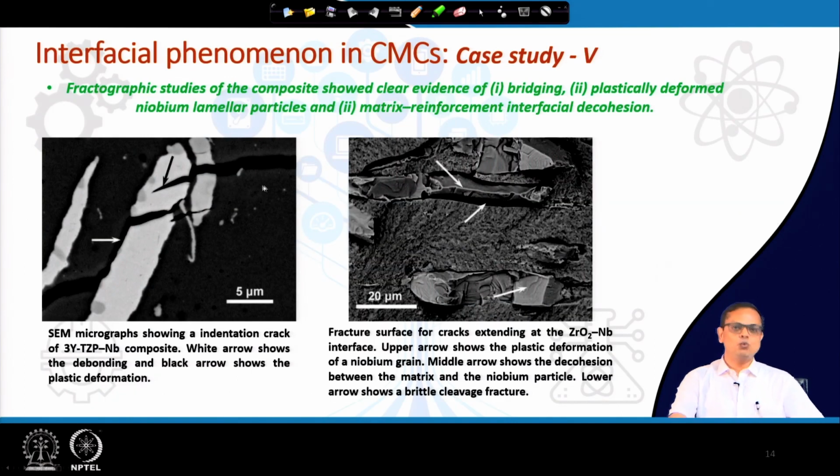So, here what kind of different phenomena are taking place to improve fracture toughness are nicely described. So, you see there are a few things that are happening. The first thing we are seeing here is the delamination. That is the classic way of improving fracture toughness. Okay. It allows a certain amount of delamination, but it is not completely delaminated. You see, okay, it is delaminated and then there is a branching kind of taking place in the crack.